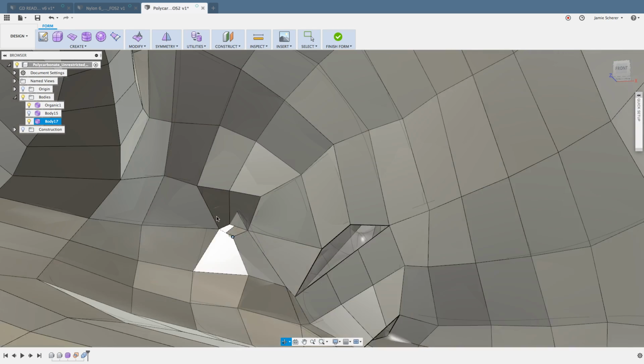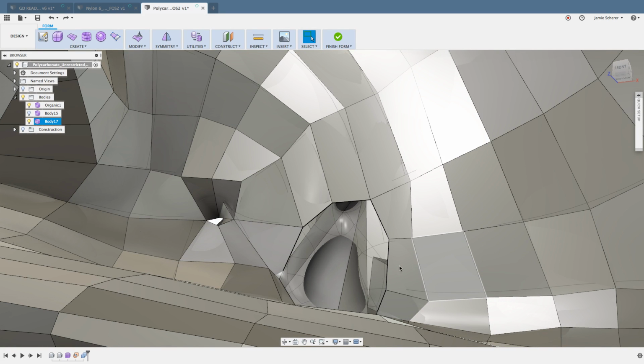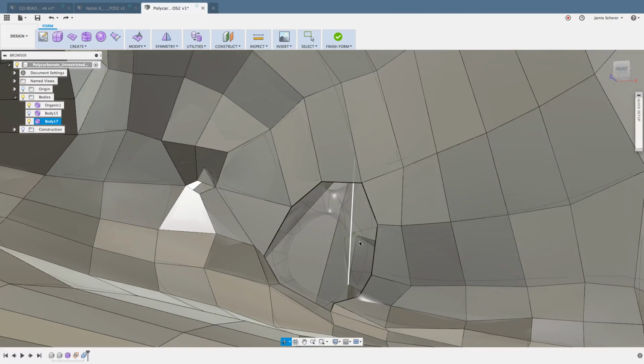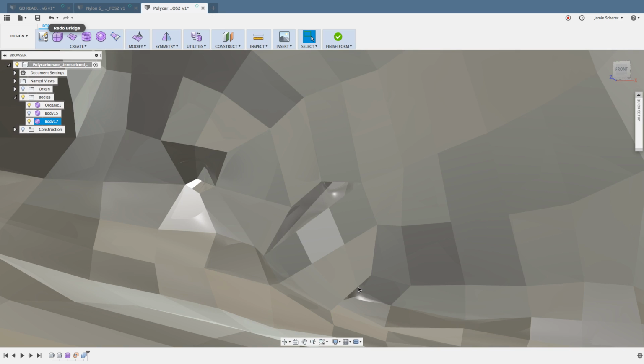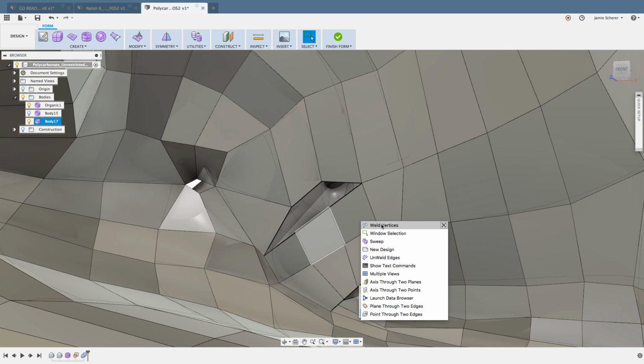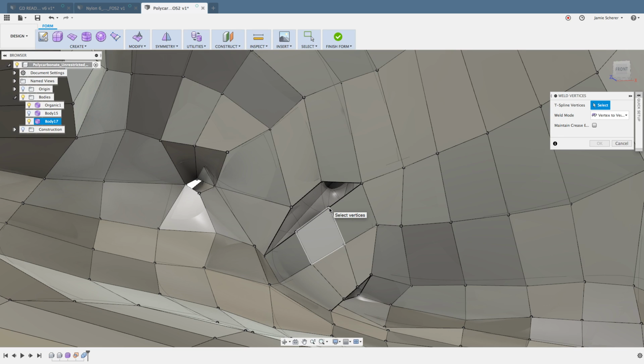So coming back around, now I just want to go back and weld together those last faces. I'm going to go through that final step one more time, because I accidentally escaped out of it, and it's just weld first selection to second selection. So the first vertex moves to the second vertex, and we'll just do that here 4 times to make those selections.